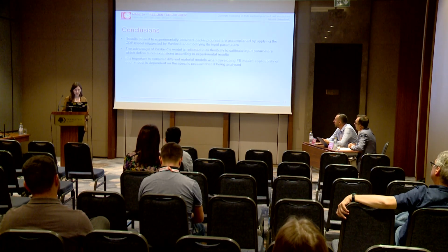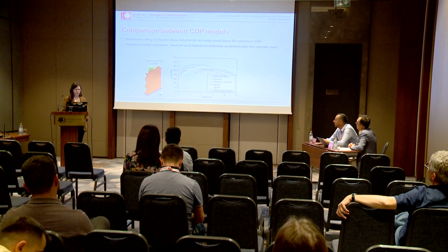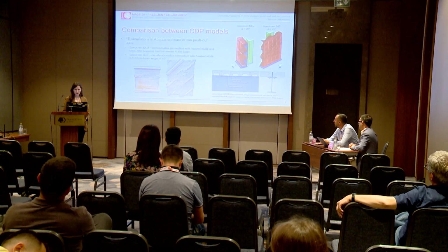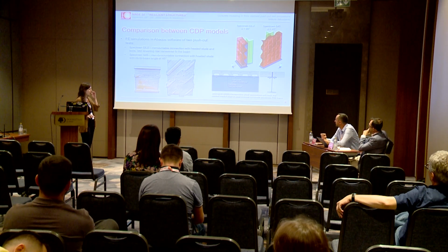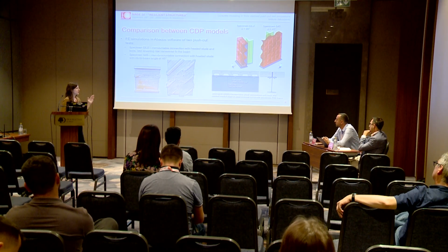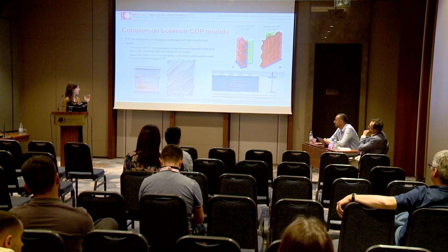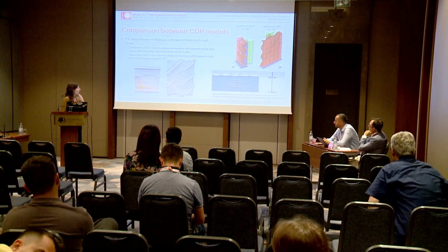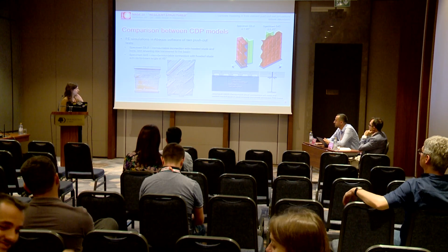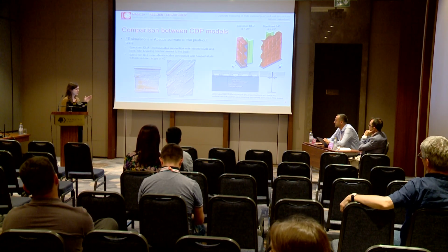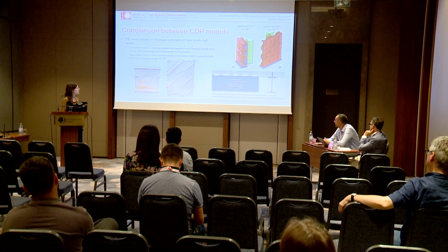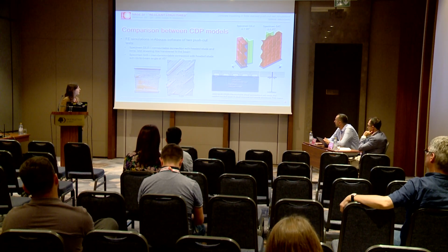Yes, here I used solid elements for all of them. Even for the steel sheet? No, shell elements are for the profile steel sheeting, although I think modeling of the profile steel sheeting is not so important for this case. And I have truss elements for modeling reinforcement in the upper part of the concrete slab.